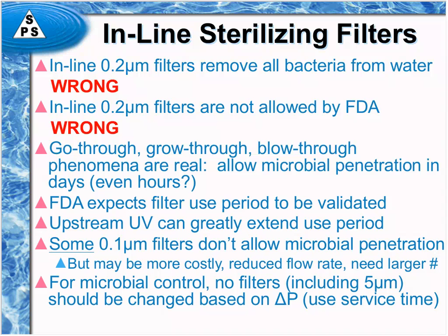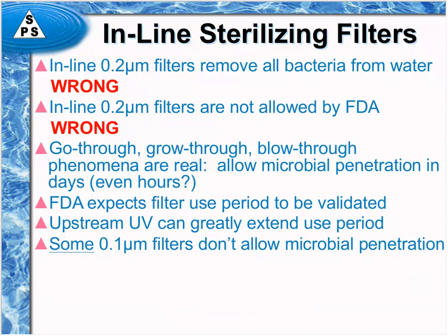Now, obviously, a 5 micron filter is not designed to hold bacteria back, but what it can be is basically a solid-state fermenter, if you want to call it that, where it grows biofilm on the surface of the 5 micron matrix that's in there. And eventually you'll be releasing more bacteria downstream than are actually impinging on the upstream side. And so just be careful about long-term use of filters, no matter what they are, and never, ever, ever base it just on delta P.